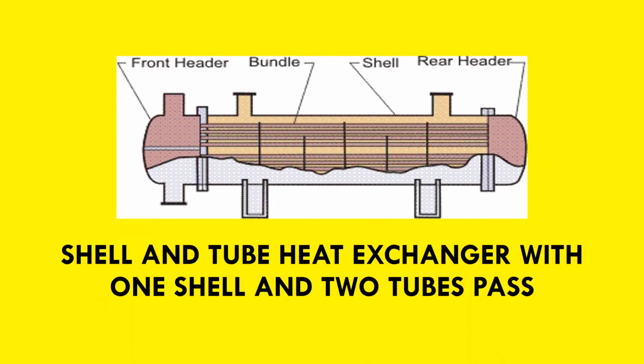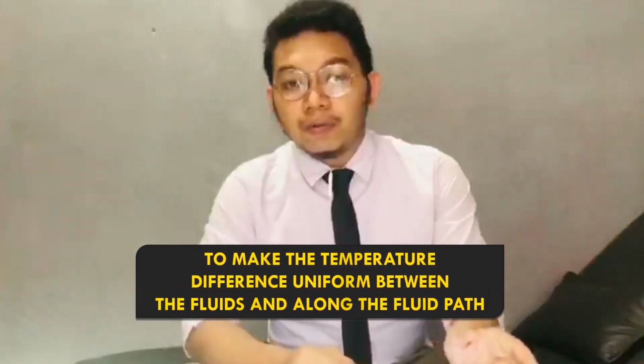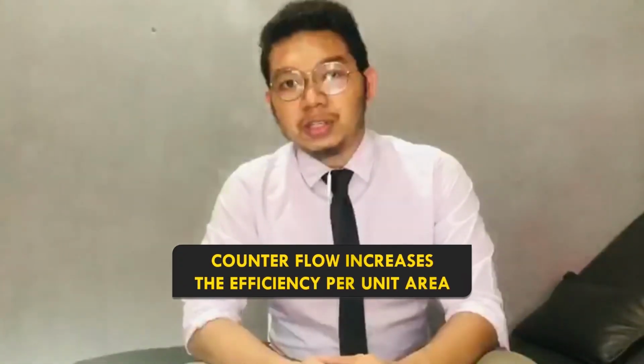For this integrated design, we choose to use the shell and tube heat exchanger with 1 shell and 2 tube passes. Counter current flow of cooling water is used to make the temperature difference uniform between the fluids along the exchanger. Compared to the plate heat exchanger, this kind of heat exchanger is more appropriate and widely used in industrial applications. It is also very flexible for designing coolers. Counterflow also increases the efficiency of the heat exchanger per unit area.